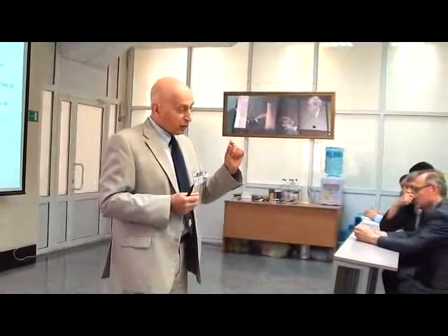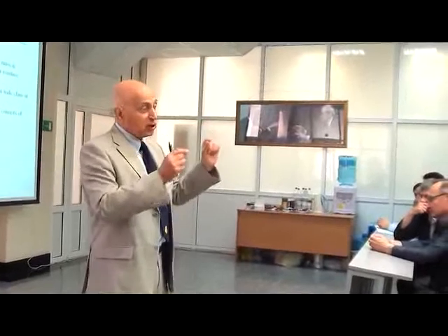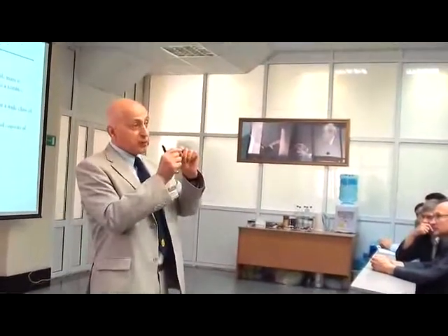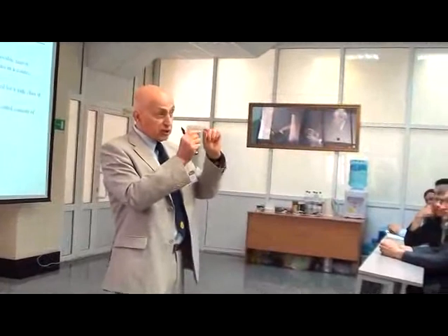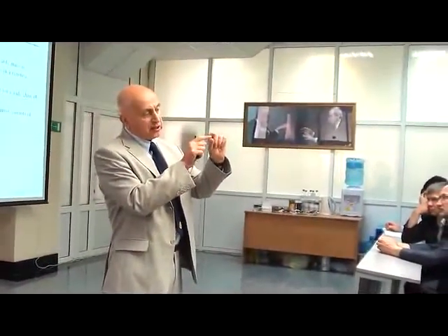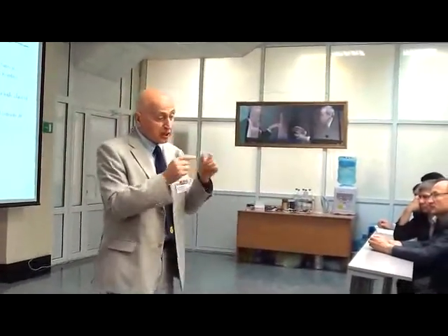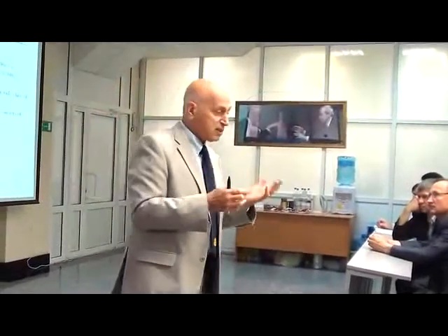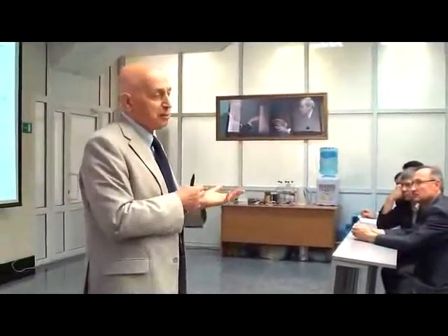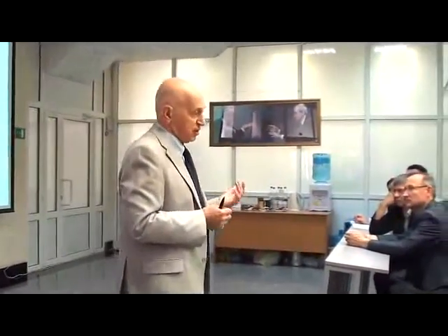For example, for the case that we considered of a capsule moving in a tube, it is quite enough, because when the capsule moves in a tube and inside, due to electromagnetic force, there are very high frequency vibrations of a mass, then the friction between this capsule and the tube consists of dry friction and a bit of linear friction. So for some cases it may be enough. And it gives you some idea how to start with these problems.